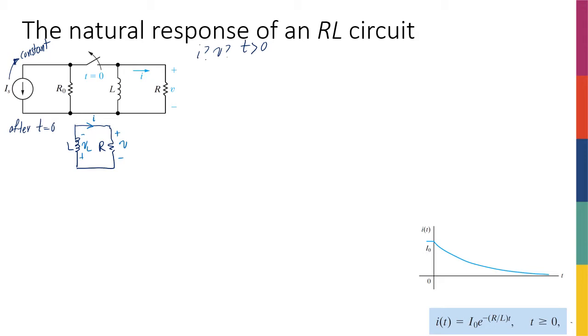It's a simple resistor and inductor kind of circuit. That's pretty much why we call these RL circuits. The kind of circuit that we are analyzing always contains one inductor L and one resistor R. It might be more than one resistor, but then we know how to combine more resistors into one using series and parallel combinations. So at the end, we're dealing with one resistor and one inductor for any of these kind of circuits.